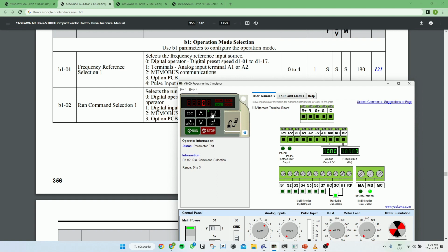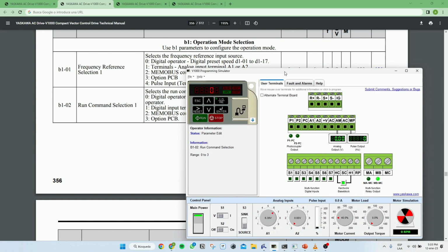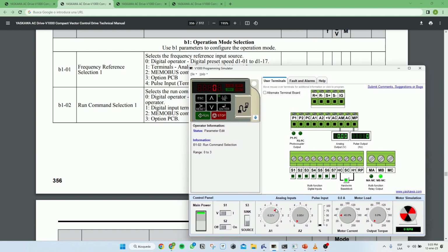So if it's not forced, which is the variators that have these functions to force them, in case they need to move for emergency issues, or maybe that they don't know anything about drives, they don't know how to go into the parameters, or something that may have happened with the signals that they have to start it forcefully, then that's the point where they're going to press the local button, we're going to send out the signal, and that's when the drive can start. Okay? So this is what this is for.